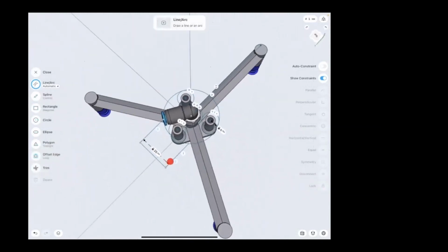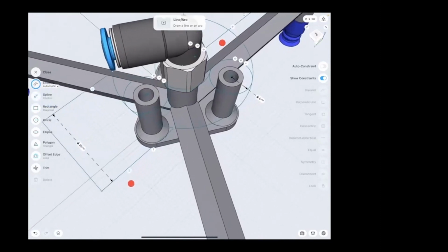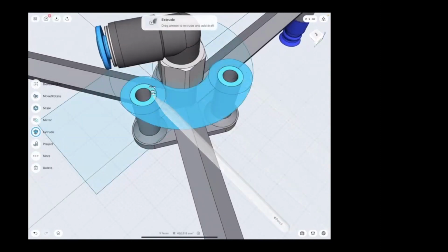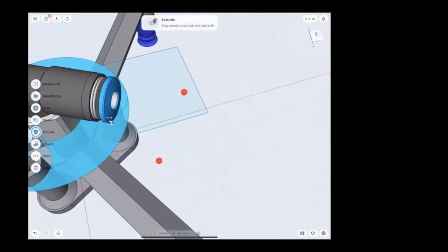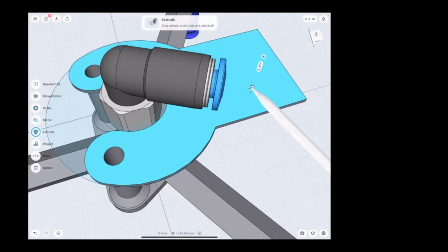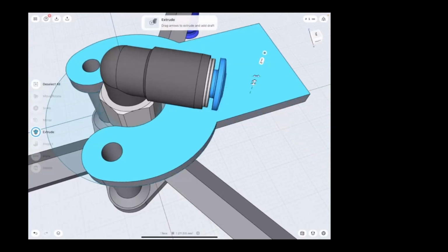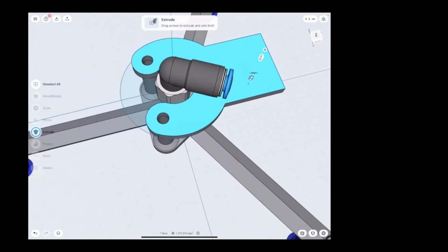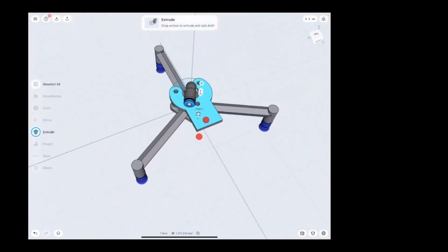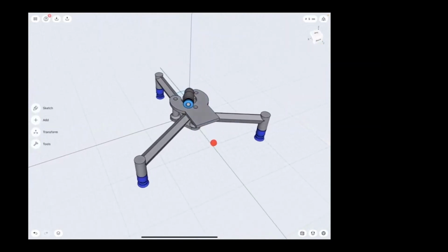And then I can rotate away the view again, and I have a lot of cross-section to work with. After selecting these cross-sections that I'm looking to extrude, I can select those and extrude upwards by 3 millimeter, and I'm looking to create a new body, as this body may not be 3D printed in each cases. It is perfectly fine if it's laser cut, for example.